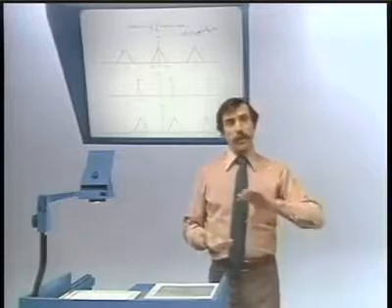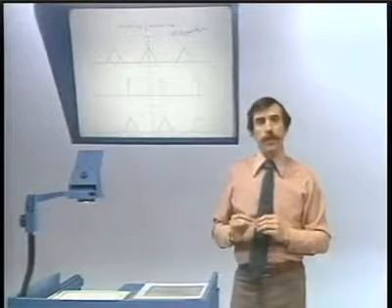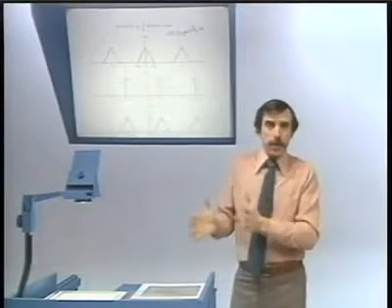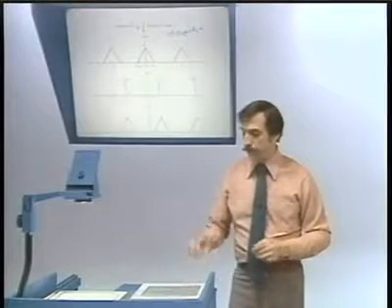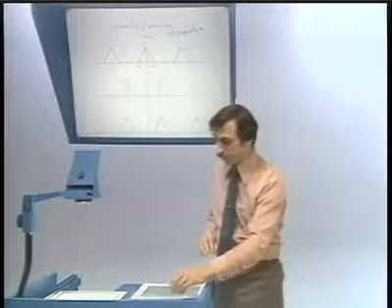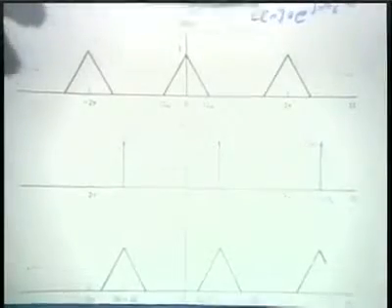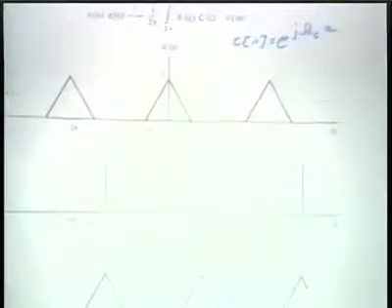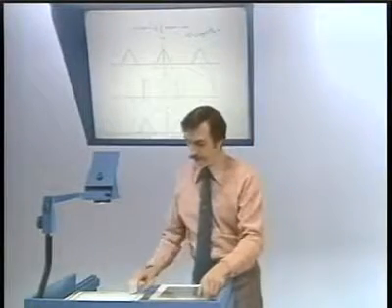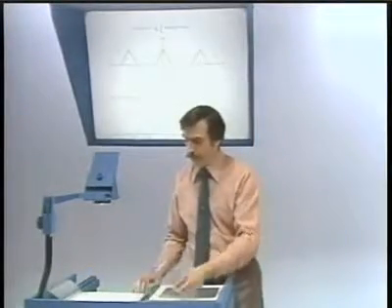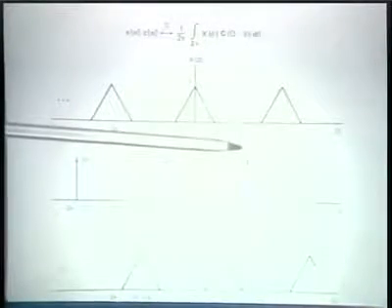Now, in the continuous time case, we demodulated when we had a complex exponential carrier by essentially just shifting the spectrum back. And in fact, in the discrete time case, we're able to do exactly the same thing. So if we were to replace c of n, which is e to the j omega sub c n, by c of n equals e to the minus j omega sub c n, the resulting spectrum would be an impulse train, as I indicate here.